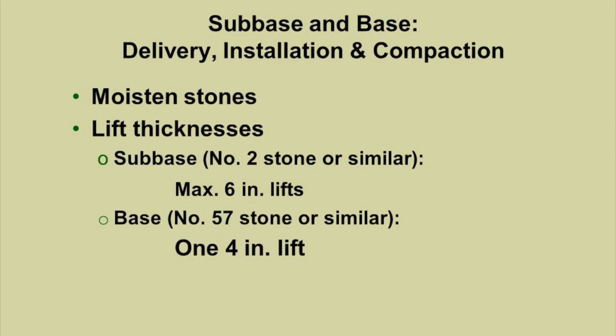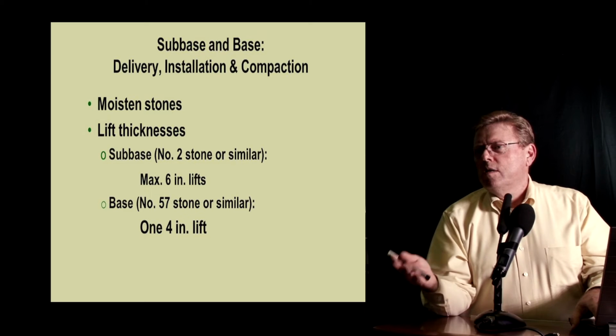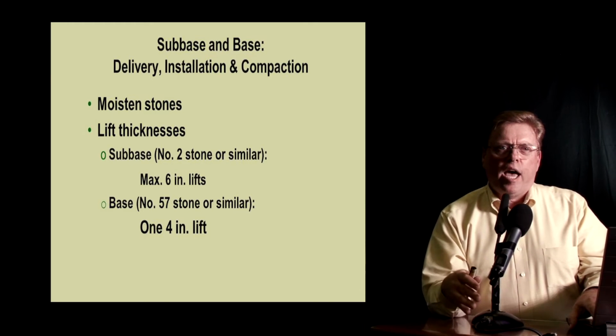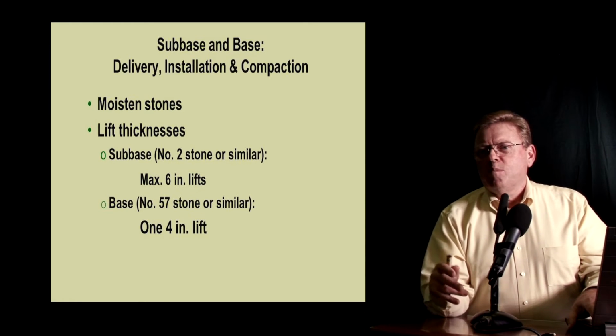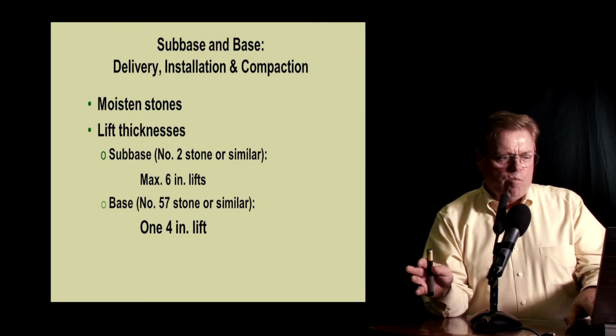Okay, the compaction is just like, and we've been through this, basically in pavers and with some of these aggregates, you look at in the base courses, you're not going to get a nuclear test done on an open graded aggregate. You're not going to find anything. There's ways of doing it in what they call the backscatter mode, but basically it's a prescriptive path.